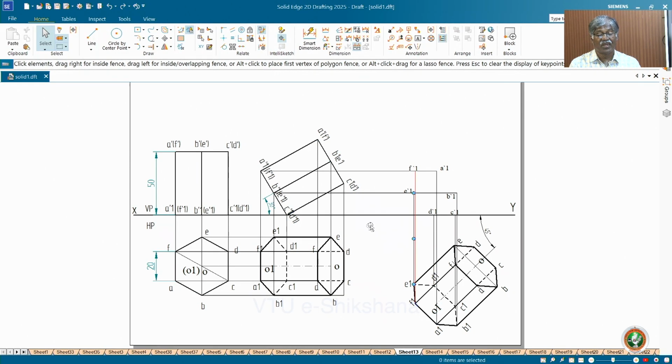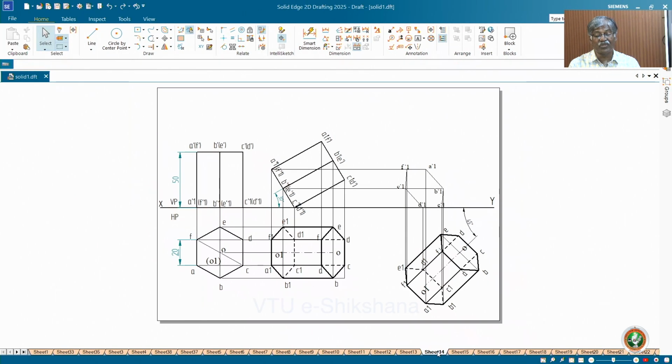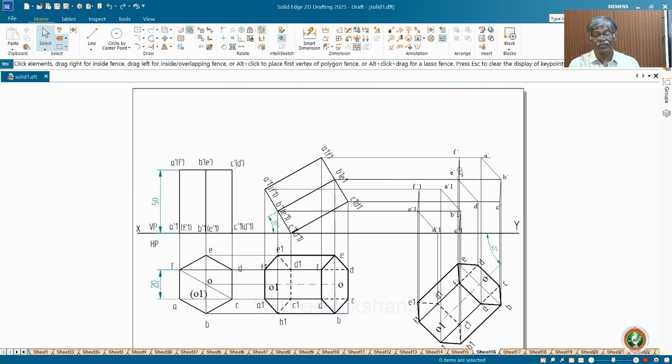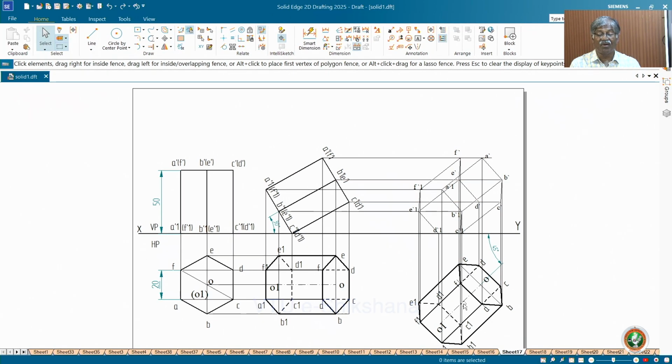Okay. Now this is the corner. These are the corners of the base. I have drawn projections from the top view, final top view, and got these points. Similarly, you get the projections from the top face, the projections from the previous front view top face. Join them. Then join the longer edges, FF1, AA1, BB1, CC1, DD1, and etc. You get the figure like this. All are light lines. Okay, I have made all are light lines.